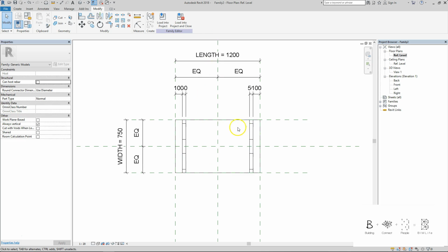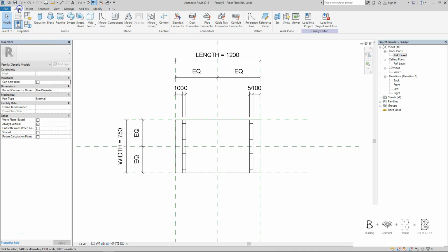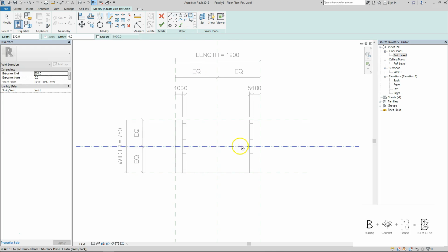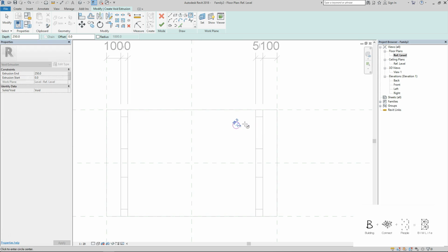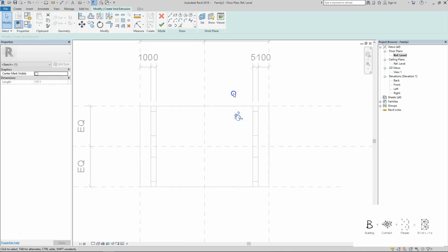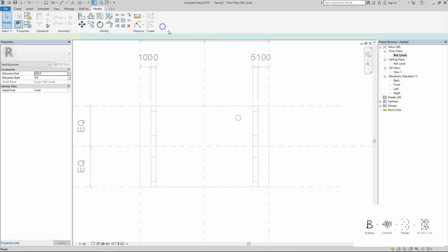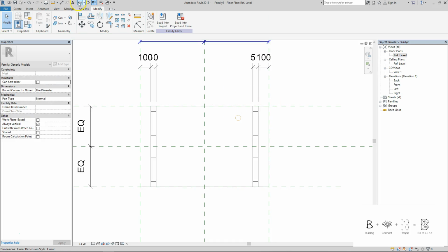And there's also a void in the uppermost right hand corner of the table. So create, void forms, void extrusion, put the circle, and the radius is 25. Okay, radius is 25. I don't care about the position at this point in time. I just need a void that is 25 in radius, as you can see here. And it's non-parametric, so I don't have to create a dimension or a parameter for it. Just leave it here. And it's going to go to the 3D view.